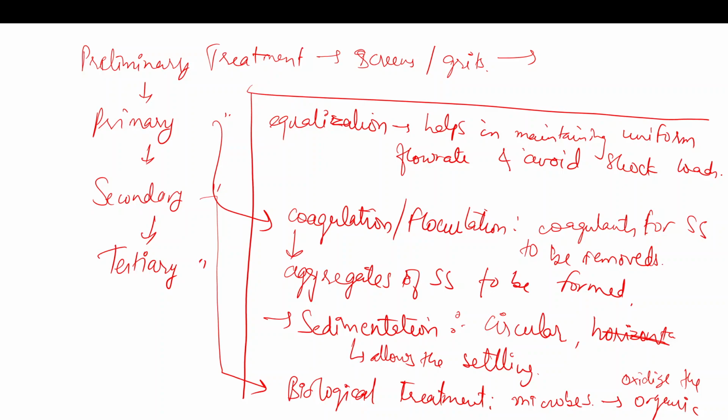So if you have higher COD and low BOD, biological treatment might not work, and you will require tertiary advanced oxidation processes, which are nothing but the oxidation of non-biodegradable organics including pharmaceuticals, dyes, pesticides, insecticides, and so on, right? Some petrochemical petroleum products as well generate high concentrations of non-biodegradable organics.